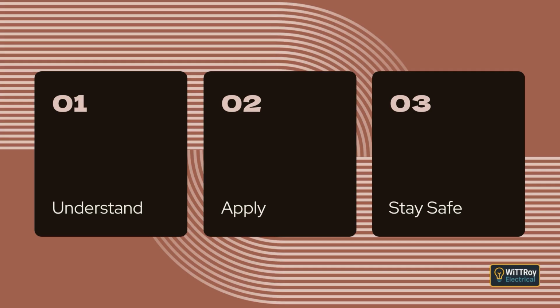Clause 3.7.2.2 Preparation for connection. Insulation must only be removed as much as is needed to form the connection. When joining insulated conductors, the finished connection must have an insulation level that matches the original conductor. Any damaged insulation must be repaired or reinstated.